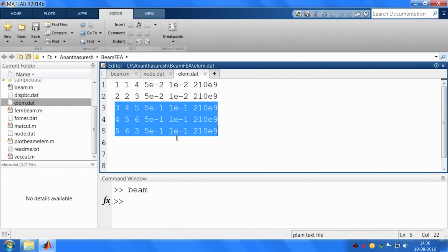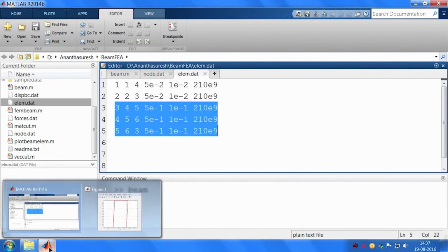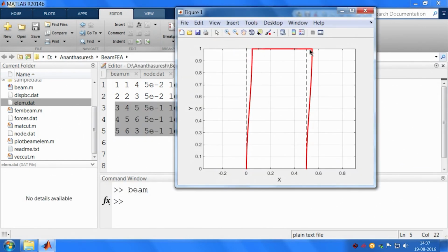This is how we can make rigid blocks in finite element analysis using beam elements. We make their cross sections much larger. If you want, you can make Young's modulus very large, whichever. What matters is E times I, Young's modulus times the second moment of area. So, you can make either of them or even both of them very large compared to the flexible segments. So, you can create a rigid block. With that, we are able to get the deformation like this.